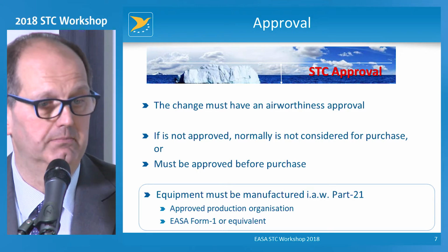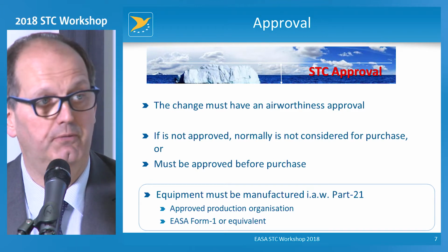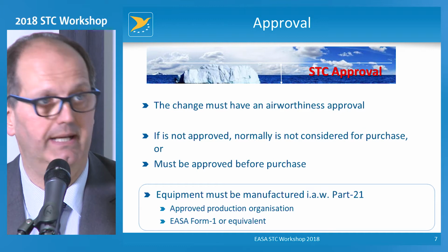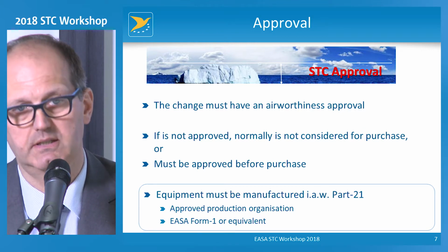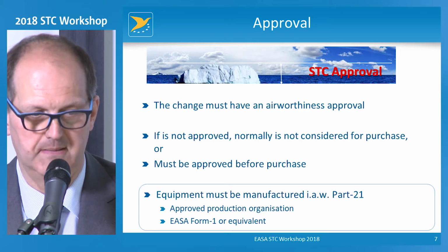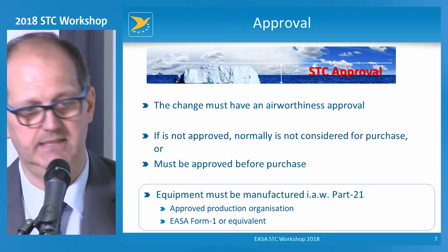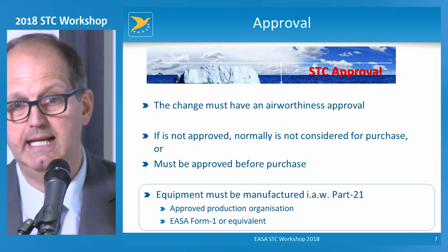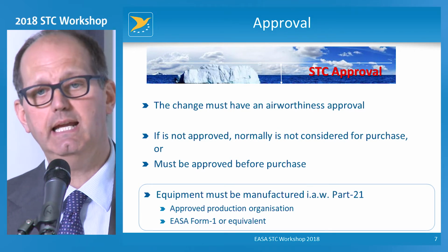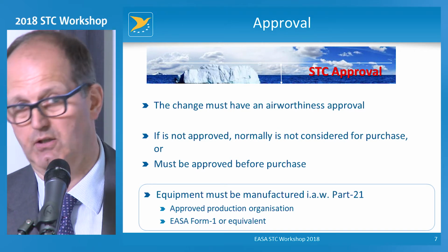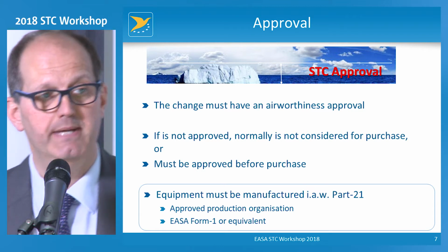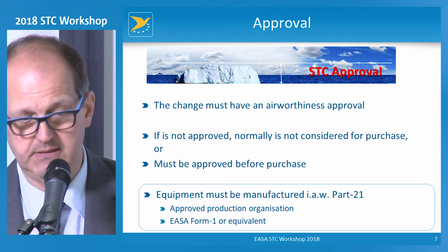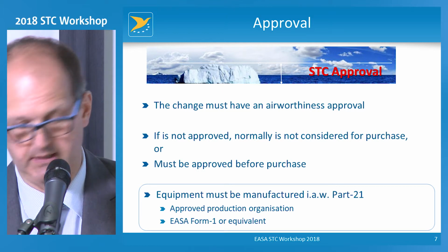One thing I would like to make clear is that also the manufacturing of the change, you may have elements, must be covered by Part 21, meaning that must take place in an approved production organization. And the change itself or the elements composing the change need to be covered by an EASA Form 1 or an equivalent.